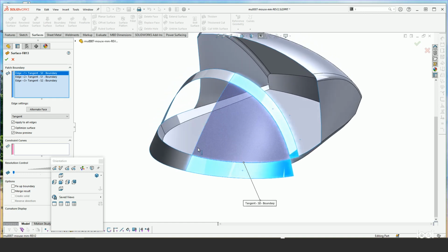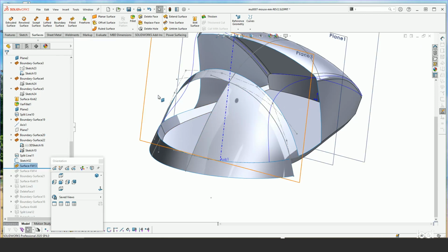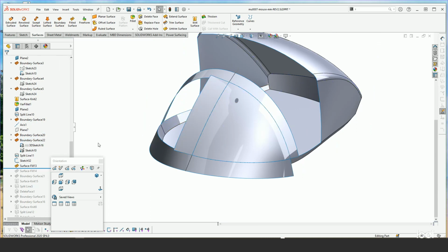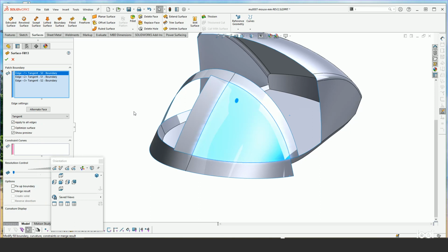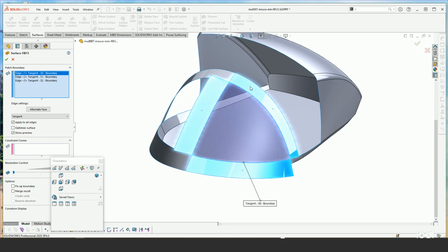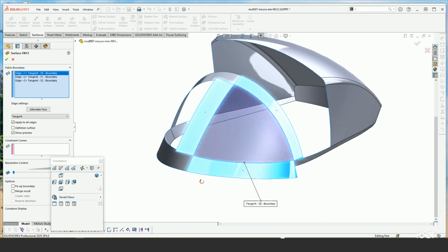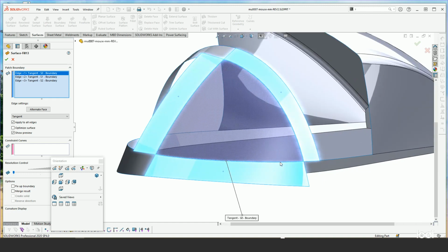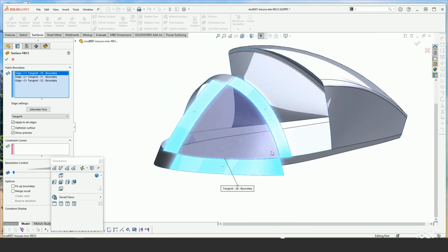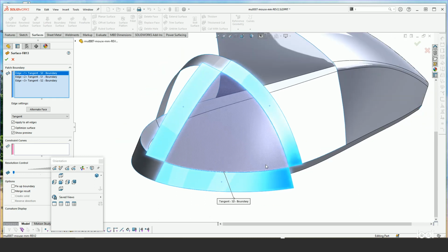And furthermore, it's not actually that sketch, but it's yet a third reference surface. So if I show that, I now have a fill surface completely constrained by tangent exterior reference surfaces and driven by those. And that is the best situation that you can get for fill to get a predictable result.